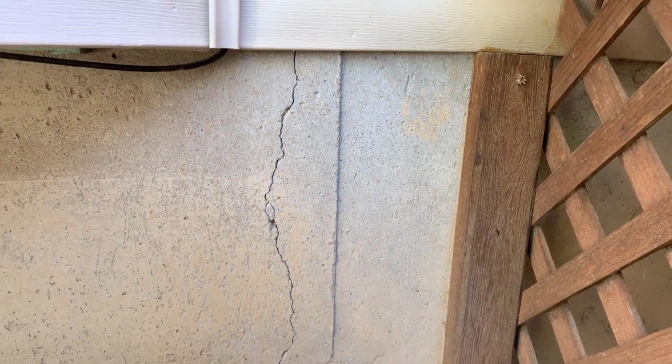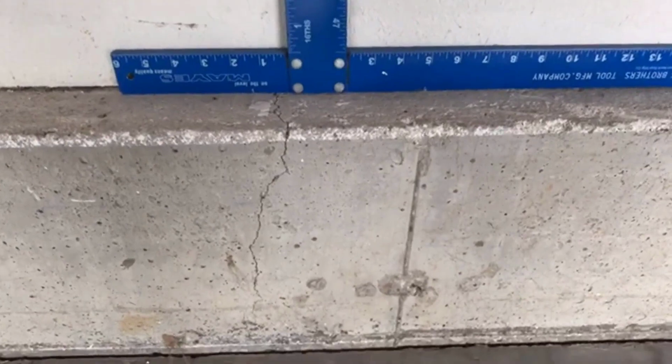Hi, I'm Randy with RLM & Associates. There are three basic types of foundation cracks: dry shrinkage cracks, settlement cracks, and shoving cracks. This video covers dry shrinkage cracks. Here's a short video clip showing a typical dry shrinkage crack. As you can see, a shrinkage crack is not typically straight but jagged like a lightning bolt. These cracks go completely through the foundation wall and should be the same on both sides.